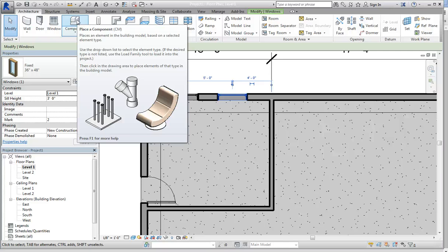such as toilets, bathtub, shower, kitchen stuff. All architectural plans, they have to include bathroom stuff. You could write that down. And they have to include kitchen fixtures because it's part of electrical and plumbing. Stuff like beds, desks, chairs, those are optional and nice to place because you get a sense of space and if things will actually fit.